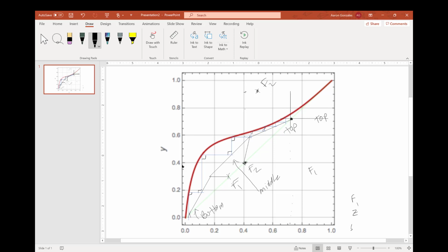So look at this portion closer to the distillate concentration. You can see I created lines that are a little bit more accurate, that are closer to the 0.72, and I made lines coming out this way and coming down this way. So when you cross it, that's when you stop. If you notice right here, this last step going up crosses your distillate concentration. So you stop. As soon as you cross, or for the opposite, if you're going down, as soon as you cross your bottom concentration, you stop, or when you cross your distillate concentration, you also stop. So from there, we're going to stop, and now we're going to count the steps and how many equilibrium trays we're going to need.